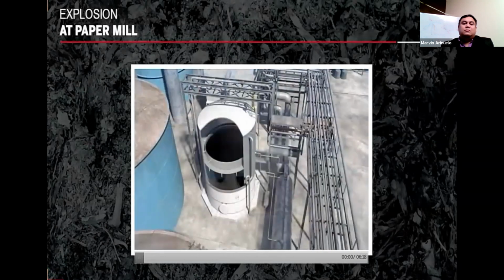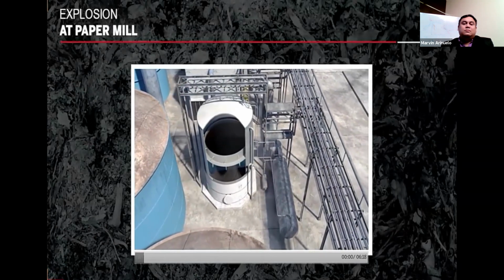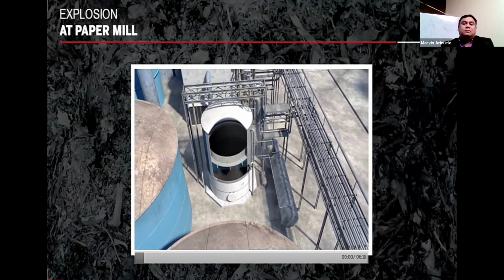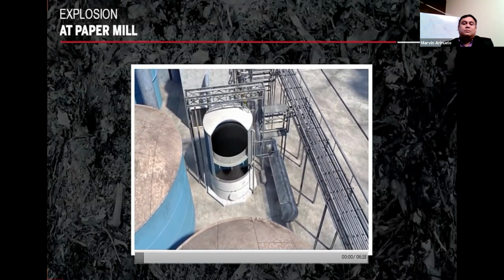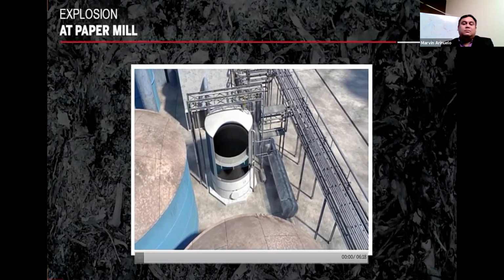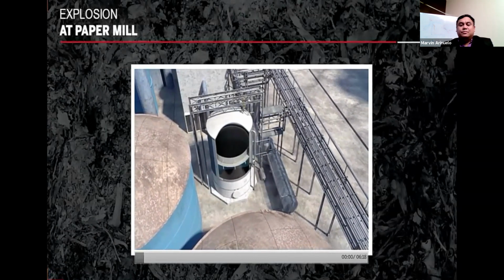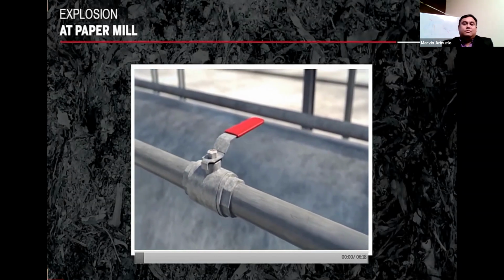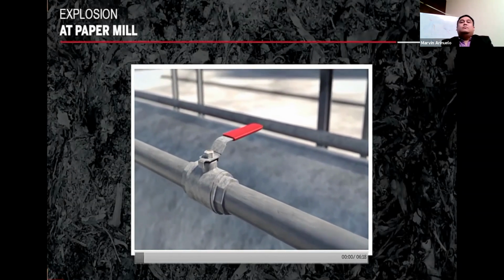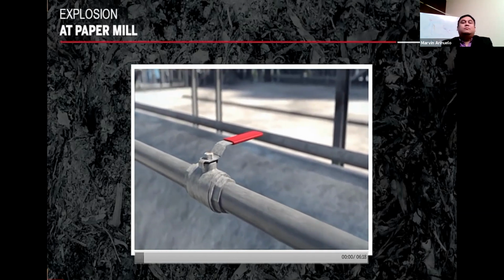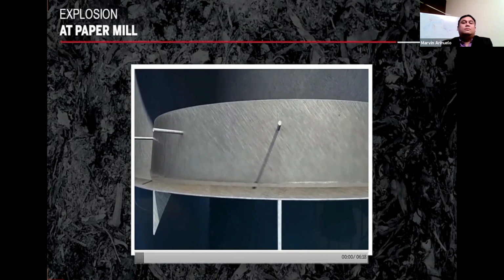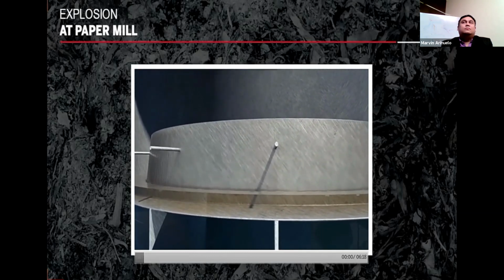But in the months leading up to the incident, the turpentine was not removed because there was confusion as to who at the mill was responsible for operation of the foul condensate tank. Due to this confusion, a valve designed to direct skimmed turpentine to the mill's turpentine recovery system remained closed for months. As a result, leading up to the incident, more flammable turpentine was present in the foul condensate tank than anyone expected.